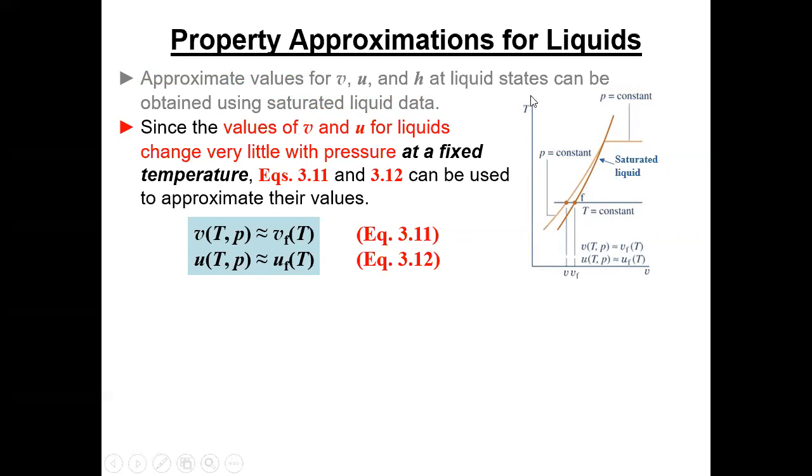So, it's temperature versus specific volume. That's our TV diagram. And this line right here is just the saturated liquid line of the saturation dome. Okay, so over here is two-phase stuff. And on this side is compressed liquid stuff, okay? So that's all that darker red. And then this lighter colored line is an isobar, okay? So that's a line of constant pressure.